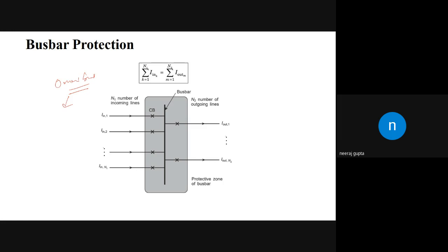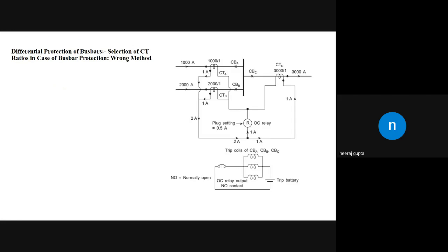However, with time, it was felt that if a fault occurs at that particular bus bar, it will have disastrous consequences because the whole of the supply is related to it. So that's why protection is provided, but very simple protection. As you already know, it is concentrated in a small area, so the only protection provided in that case is the differential protection.